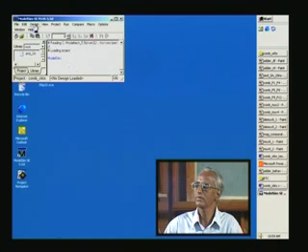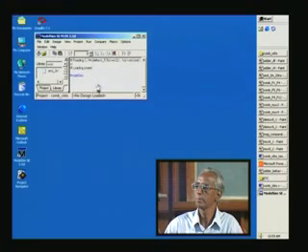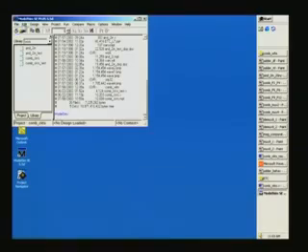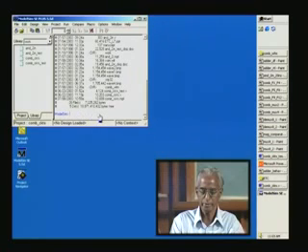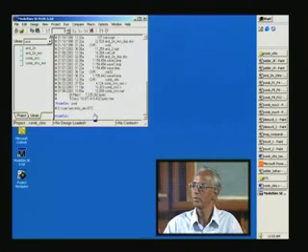So let us see where we are here. We have opened ModelSim, and using open project, the combinational circuits project is already there, and we are right there. You can just give pwd in the command mode, and make sure that we are in the user directory, the VLSI design directory. This is the directory that has all our files.